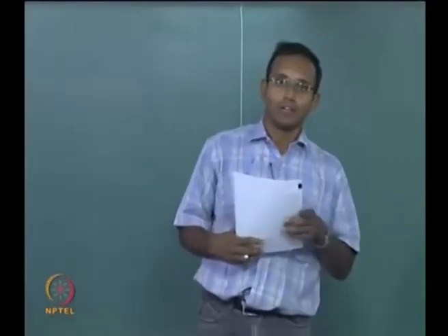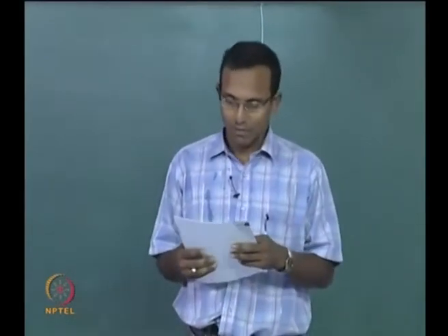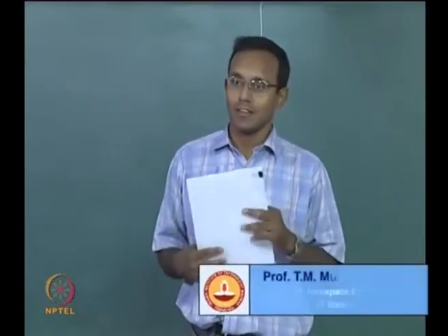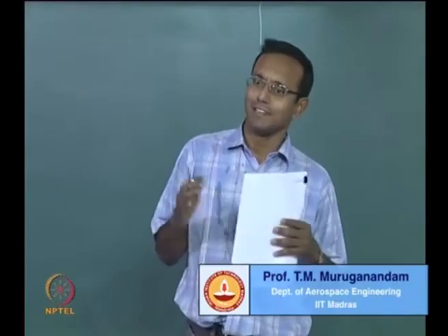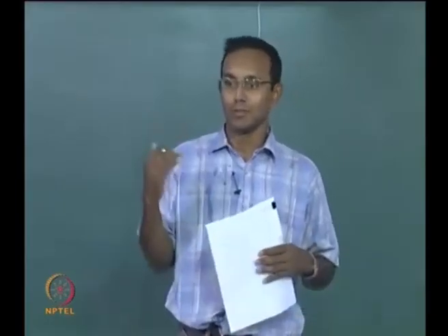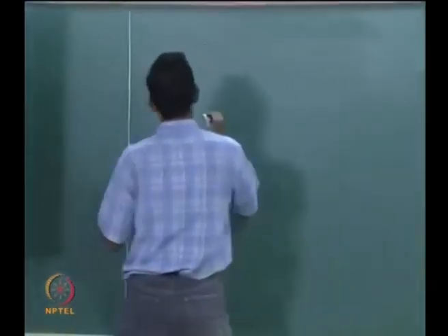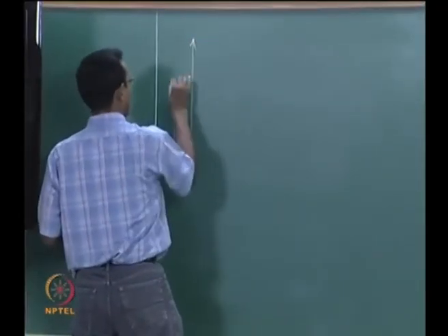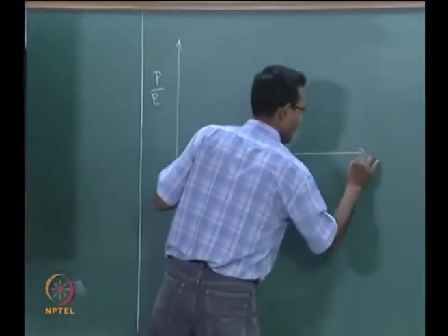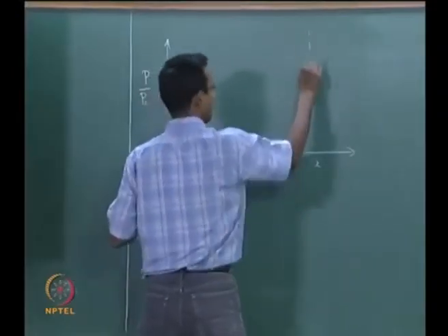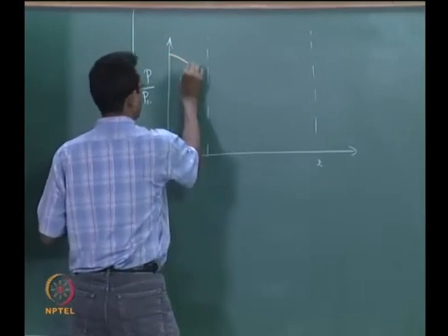Hello everyone, welcome back. Till last class we were discussing flow inside the nozzle, and if we looked at the discussion, we did not complete the full range of Pb by P0 values we could go to, and we said that we will deal with the remaining later. If we look at that particular plot of P by P01 plotted with X, and we say this is my exit plane, this is my throat line, we did this